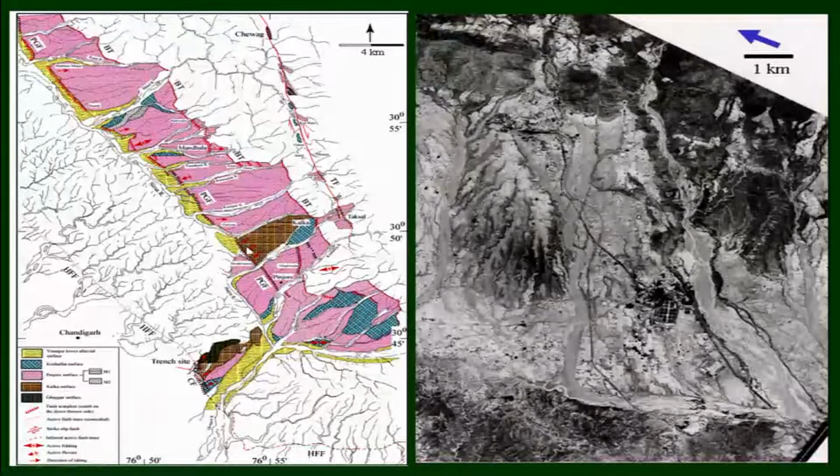prepare a detailed map. So what this includes is all the fluvial geomorphology. The colors which have been marked here are the terraces. So different terraces: this is the oldest one, so much higher terrace, and then you have the younger one as you move closer to the river channel. And all these are the parallel drainages here. This what you see is the dendritic drainage and the contact between the hills and the plain area.